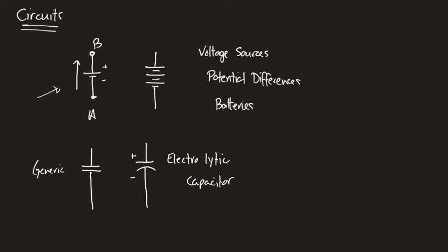The capacitors we will use in lab are electrolytic, and so you have to pay attention. The ones we have will look like a little box and have two leads coming out. One of the leads will be longer than the other. The longer lead is the positive side. The wires coming out of the capacitor are called leads.